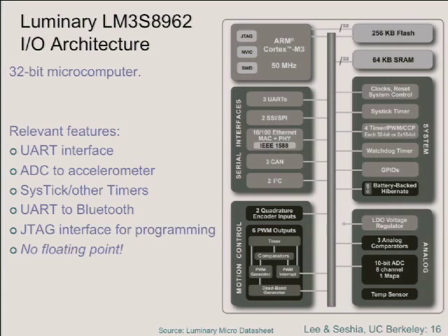The way breakpoints work is simply that it reads back the state of the processor, and if the program counter matches the location that you want to set a breakpoint at, then it stops execution. Otherwise, it allows execution to continue.